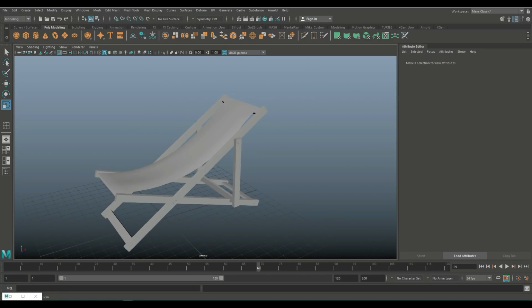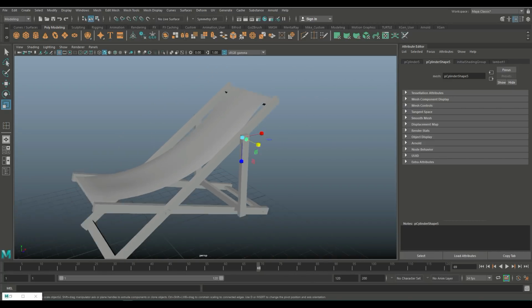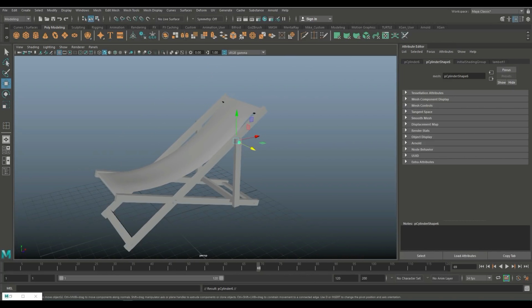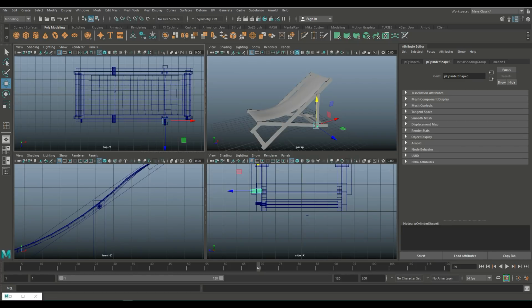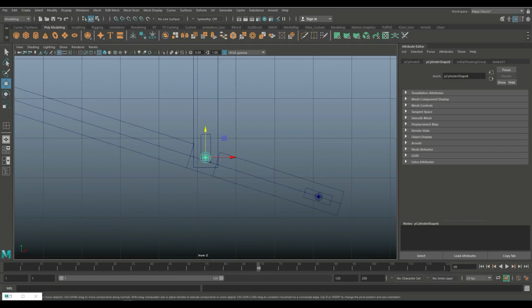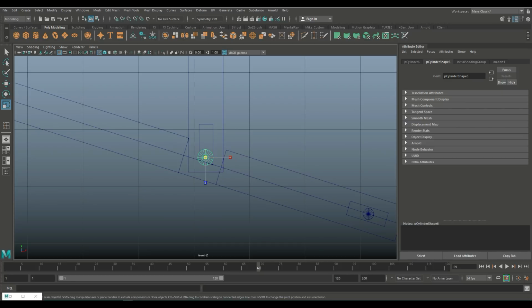And then let's see, we want one down there as well. So let's hit Control D to duplicate, W to move down. After frame, let's hit R to scale it down a little bit, W to move that up to about there.